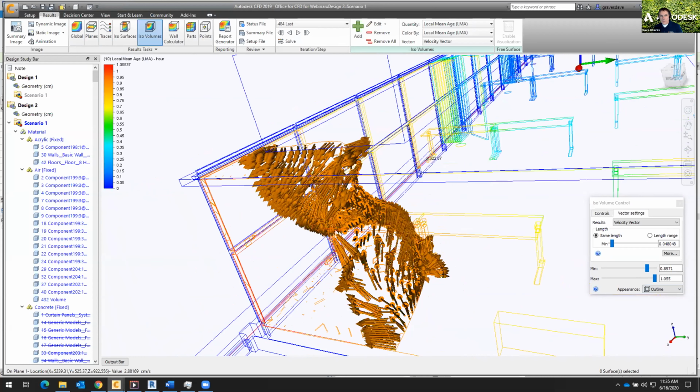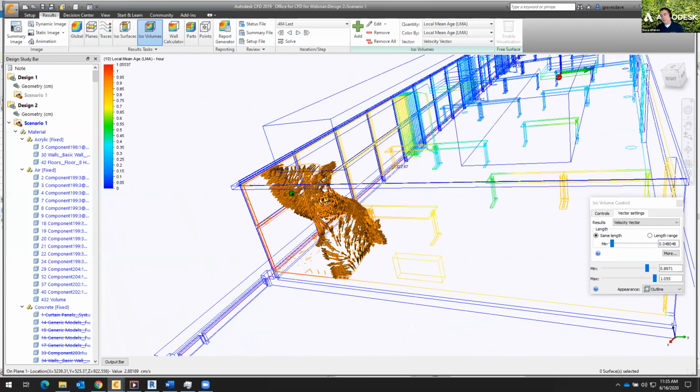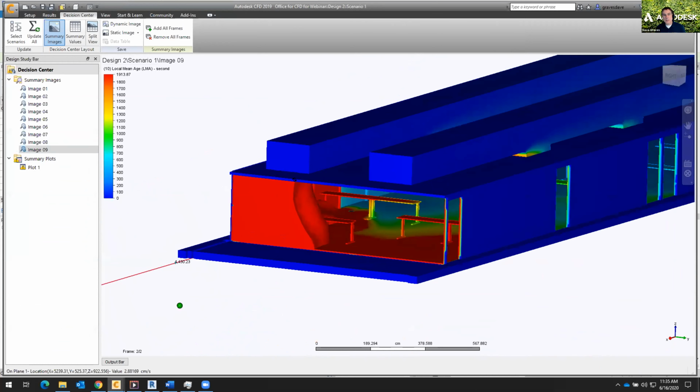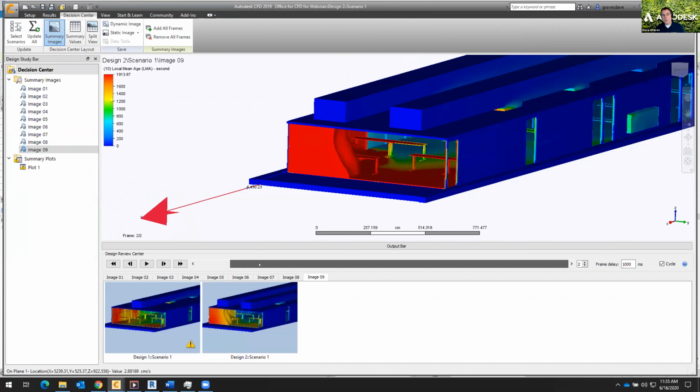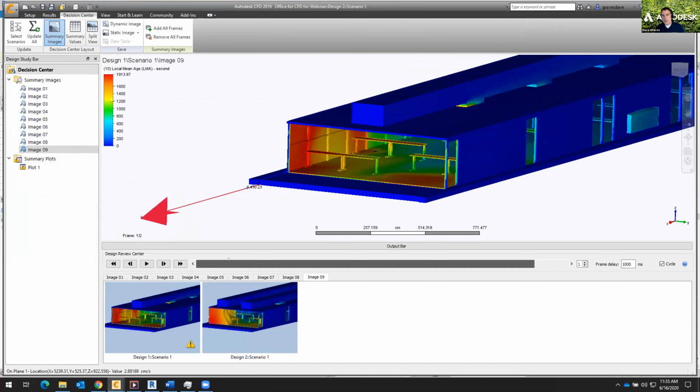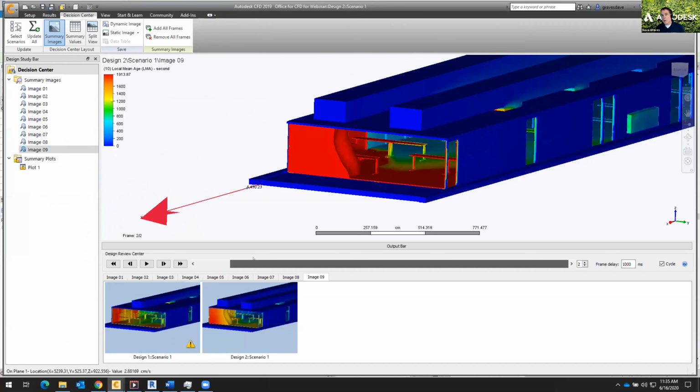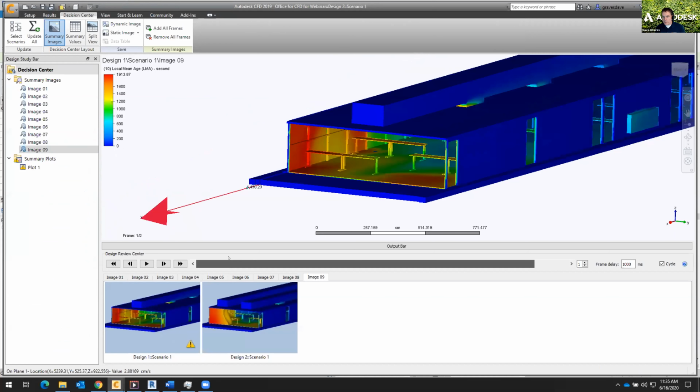The beauty of our CFD tools, what if I made a change? In this case, I had maybe a complicated two sets of air conditioning duct work here. What if I did this as a single one? You can see here's the original one that I have, and what I can actually do, again using the same model, is compare those two. So I can see how I can reduce that potential risk of recirculation in the area, which should give me some healthier, cleaner air for my occupants.